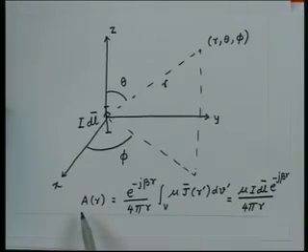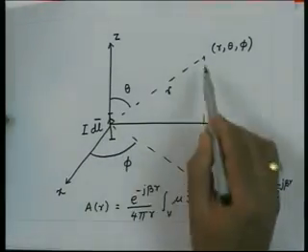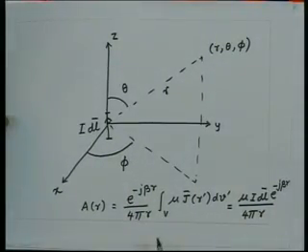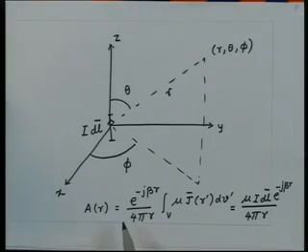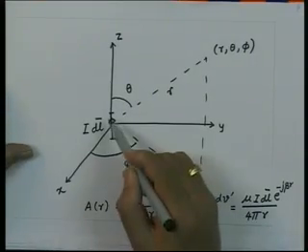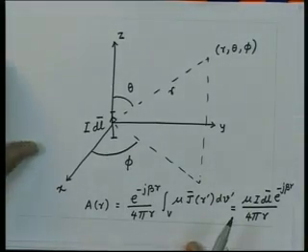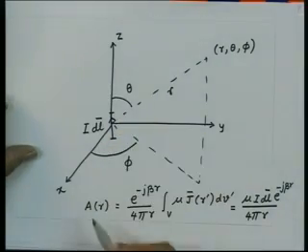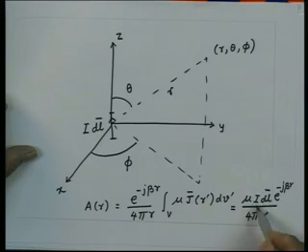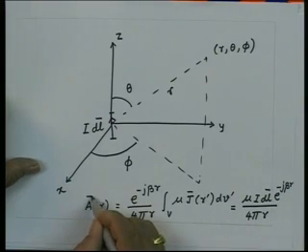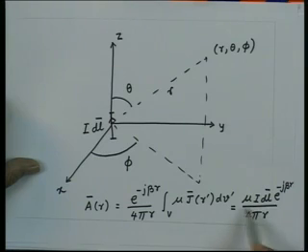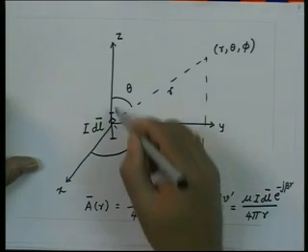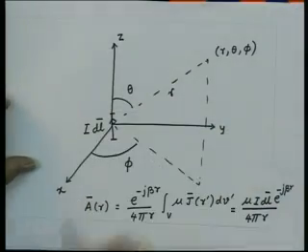So, I get now the vector potential due to this current element at this location, and as we mentioned earlier, the vector nature is only because of this current element. That means the direction of the current and the magnetic vector potential is the same, because that is the quantity which is the vector quantity, all other quantities are scalar quantities. So, we have here A which is in the direction dl, and dl is oriented in our case in the direction z.